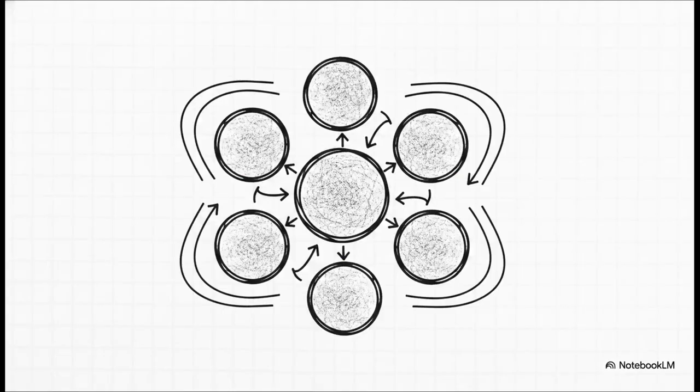By utilizing these multiple lateral cavities, the device manages to accumulate a massive amount of slow light feedback, even if the coupling from any single cavity is relatively weak. This anti-phase coupling creates that photon-photon resonance at incredibly high frequencies. On top of that, testing showed that having 4 or 6 cavities actually suppresses what's known as low-frequency relative intensity noise. So not only does the laser pulse wave faster, but it also remains highly stable and remarkably quiet, completely avoiding the chaotic instability that usually plagues lasers when they're pushed to their absolute physical limits.